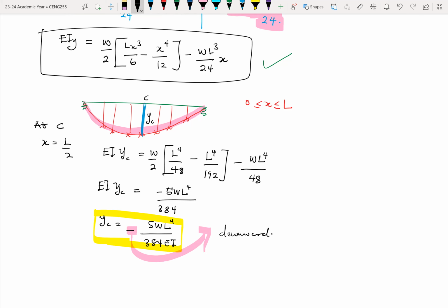So normally what happens is that you find this deflection caused by the load. Then when you get this deflection, which in this case will be your maximum deflection, you compare it with what the code stipulates. Right. So your maximum deflection should not exceed what the code has.